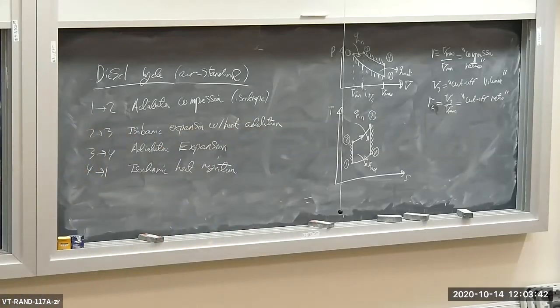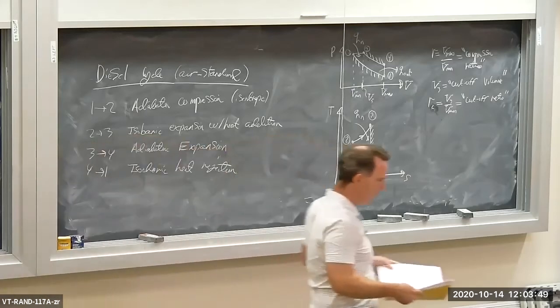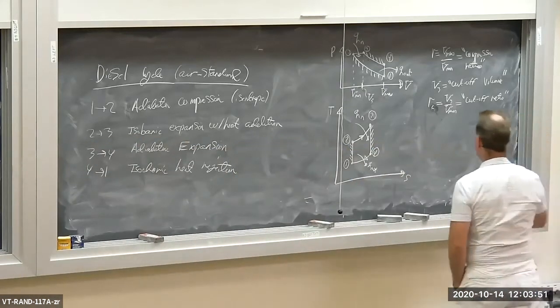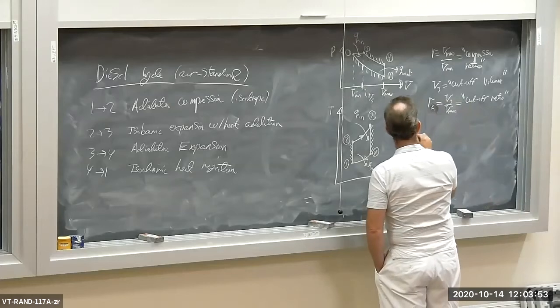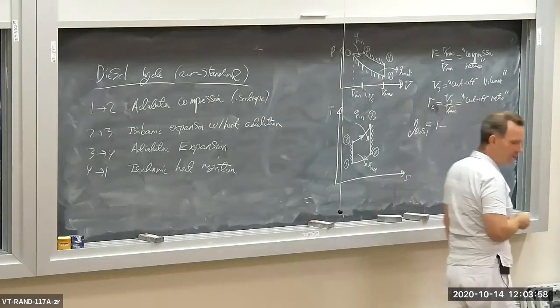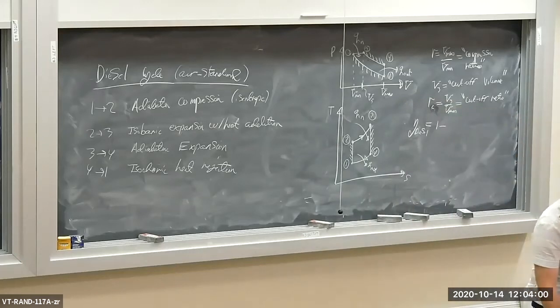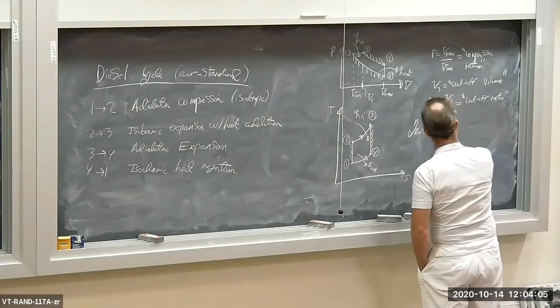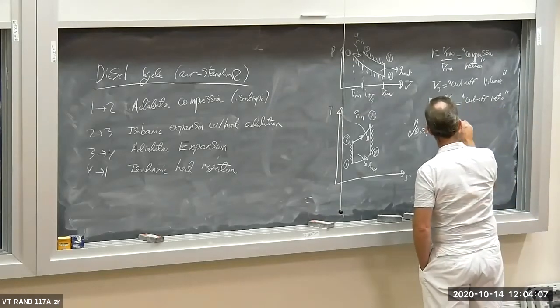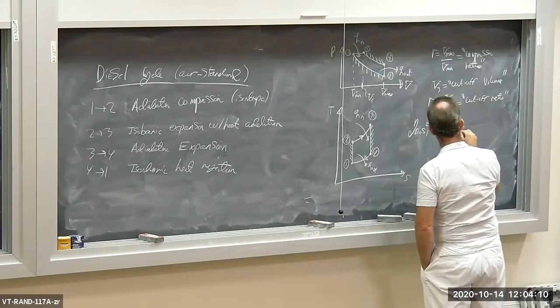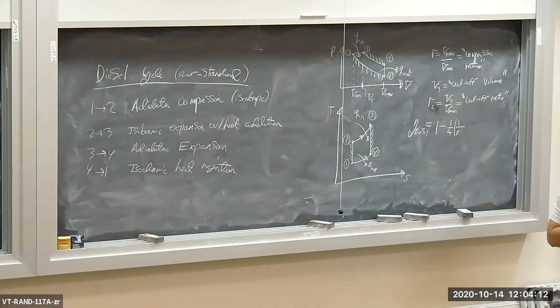Let me write down the efficiency of the diesel cycle for you. I don't memorize this stuff, so let's see here. Eta for the diesel cycle is 1 minus, and it starts looking a little bit like the Otto cycle. So I have 1 minus 1 over K, and then I have 1 over the compression ratio, R, to the K minus 1 power.